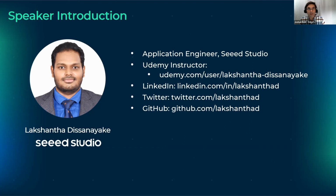The deployment option that you will eventually see in edgeimpulse.com for the Grove Vision AI module will give you a UF2, which was really meant to understand how your model is performing in a testing prototyping environment. When you're ready to deploy it into an actual application, you need to get the C++ deployment option out and integrate it into your particular coding environment. From there, I imagine you'll have to use some of Seeed's tools and their SDKs and APIs to link up to other products in their ecosystem.